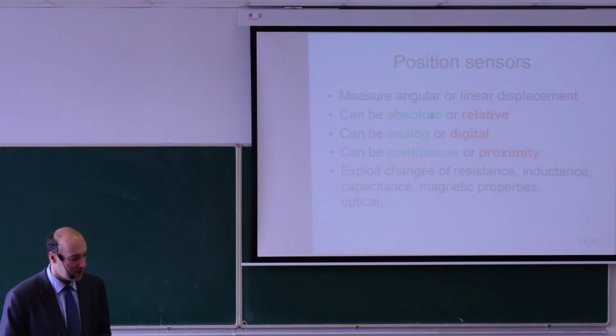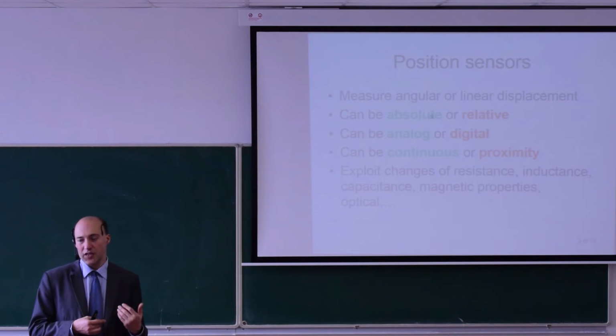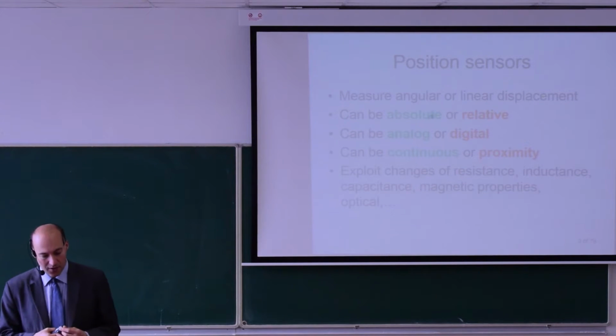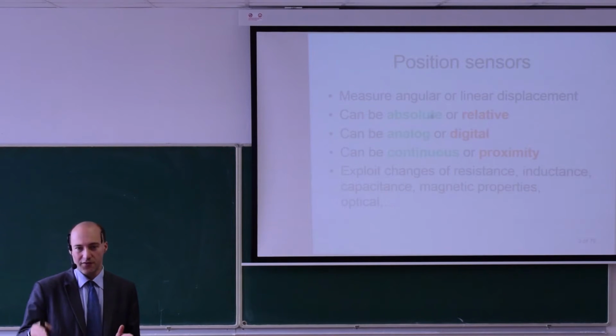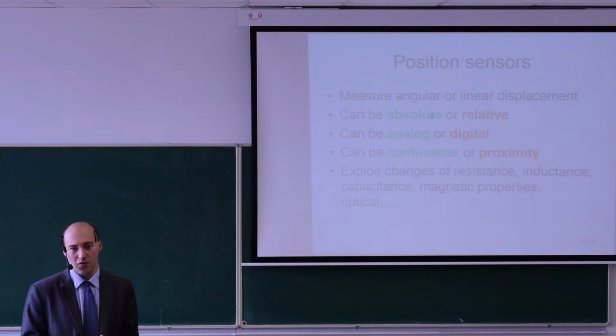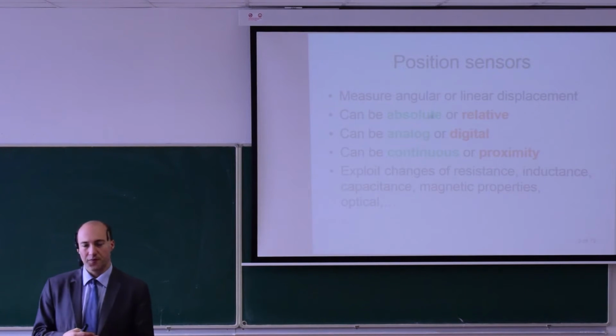On the other hand, there are many applications where you don't need this behavior. For example, CNC mills. You turn the machine on and you can go to an end stop and say, from this end stop, this will be position 0, and I can count some pulses.